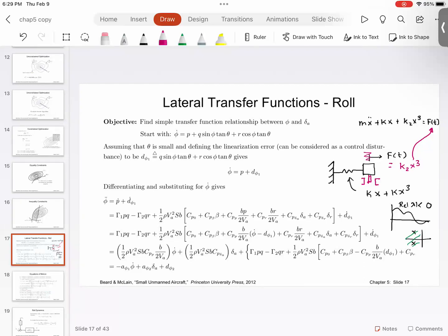I have seen folks using Lyapunov based techniques, global controllers. But if you want to design a global controller, most likely the equation that you come up with for the control law will be super complex. And you may not be able to prove that the control algorithm will work in real time, because at the end that control algorithm needs to be implemented on a microcontroller. A microcontroller has limited floating point arithmetic capability. Depending upon the microcontroller you use, you may or may not get the frame matching, which means the control law will come after the state has crossed. So remember this.